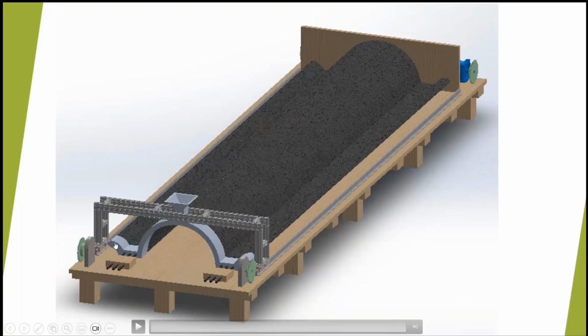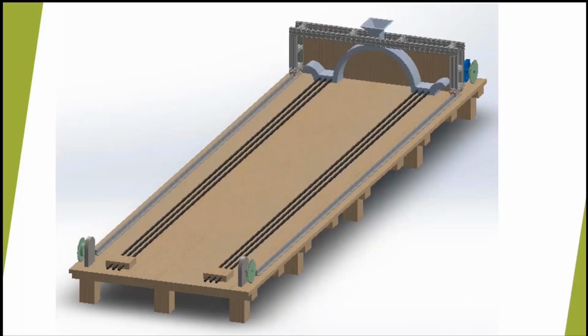So our printer, for section printing, can have any kind of nozzle. You can print any section that you want, in fact any size that you want. So this is not layer by layer. And the advantage is that you can pass the reinforcement through the nozzle, so the section that you print can already have the reinforcement in it. Whereas in the case of layer by layer, if you remember, we had to manually put the reinforcement in.